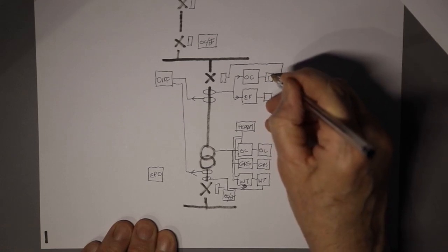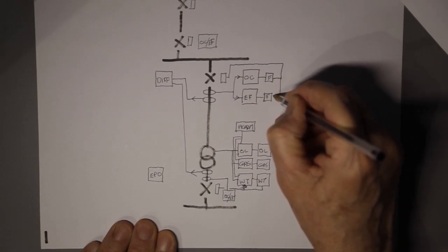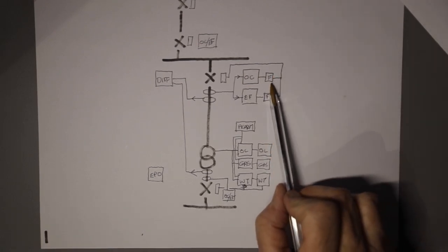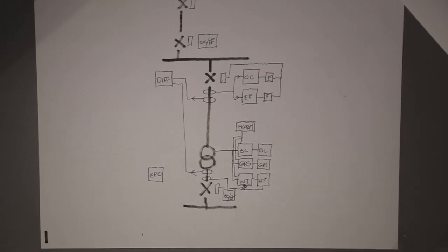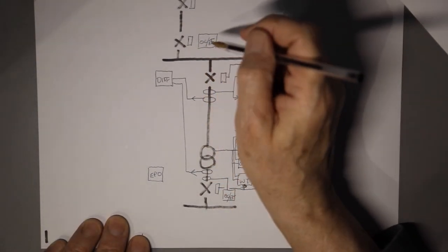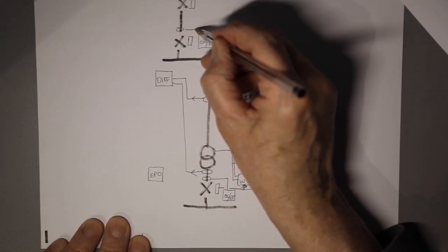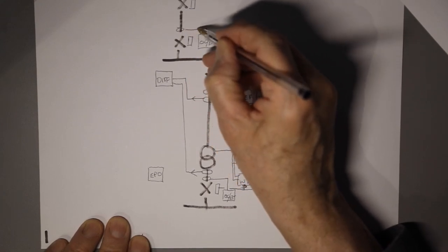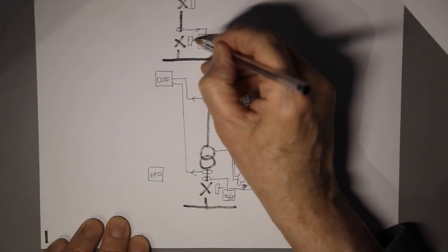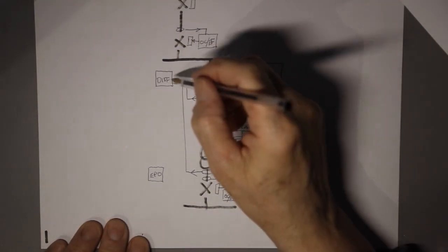Now what I'm drawing here is something we don't often get. These are flag indicators. This is quite helpful, so that if the overcurrent or the earth fault operates, they will actually flag. And if the whole site is off and the relay's dead, these could be mechanically operated relays that would flag. On the incoming circuit breaker, we've got exactly the same thing. We've got CTs, and that will operate the shunt trip coil.